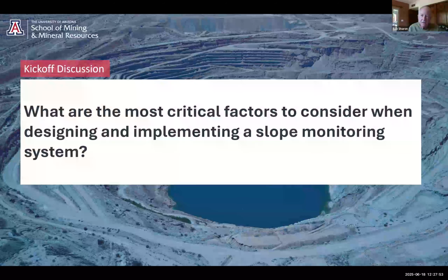Try to focus it better. There are all kinds of methods that we talk about in this monitoring guidelines book as to how to improve the quality of prism data. Once they get that in there, they can start having at least some kind of quantitative understanding of the component of movement the operators are getting from their radars or from InSAR or any other type of instrument that's giving them one-dimensional data.